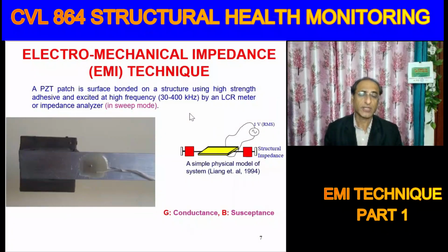So why we have chosen this high frequency? Because now in this method our target is to be able to pinpoint incipient damage. So that's why we have chosen high frequency, because high frequency means the stress waves, as we'll see in the coming slides, that is very small. So the stress waves which are propagating away from the piezo patch, they are small in magnitude, so they can very easily get affected by any incipient damage. So incipient damage means very small damage. We'll show by example. Alright.